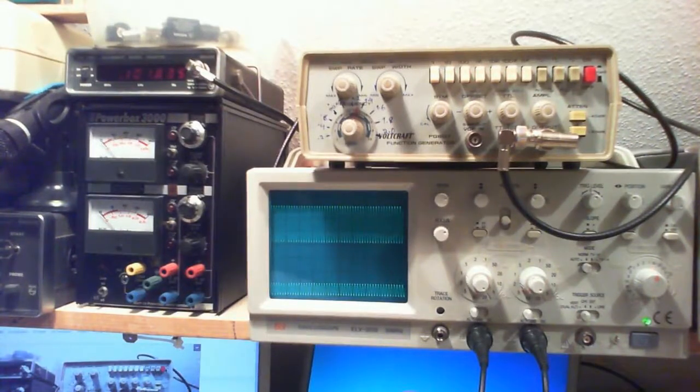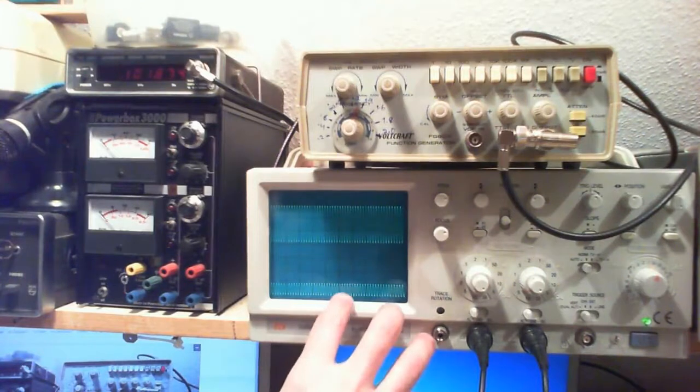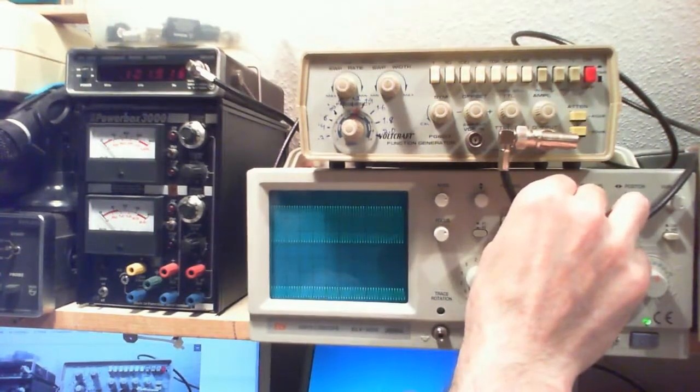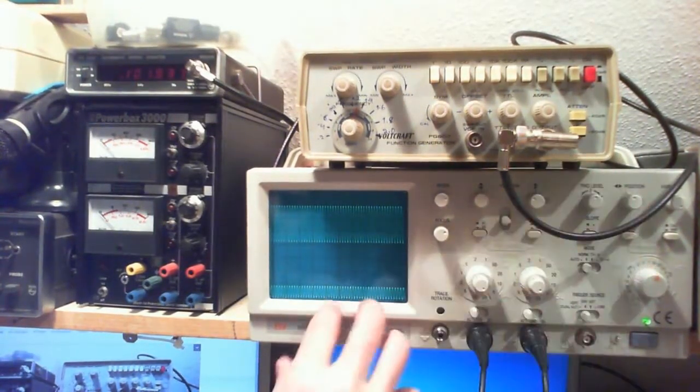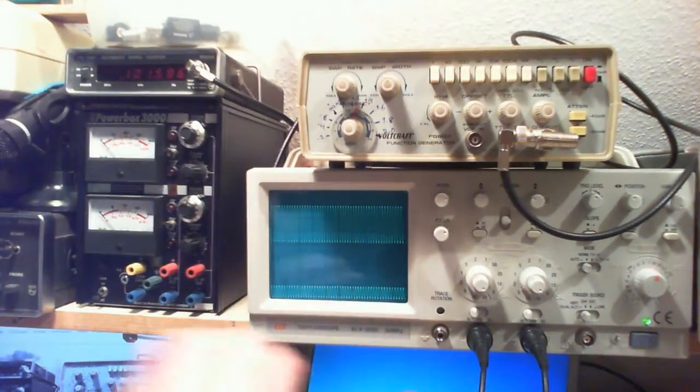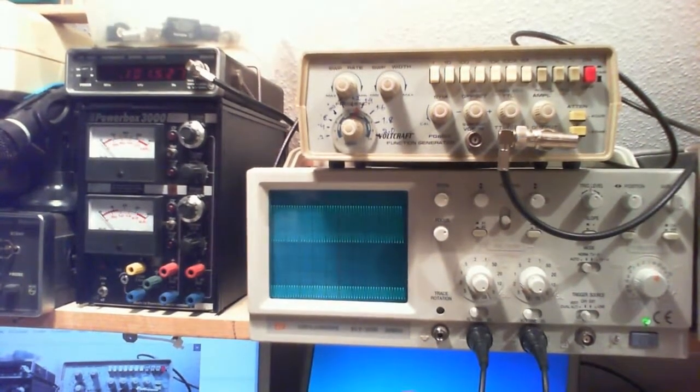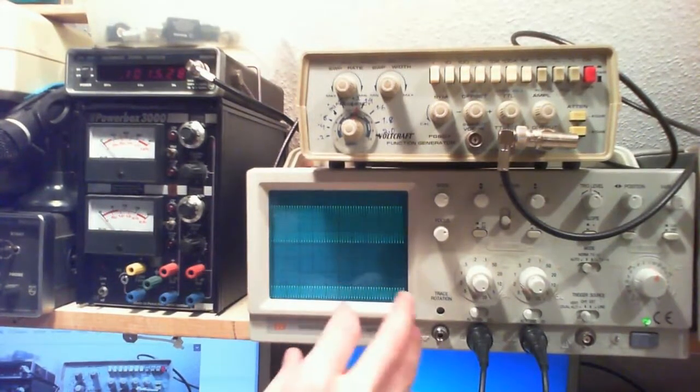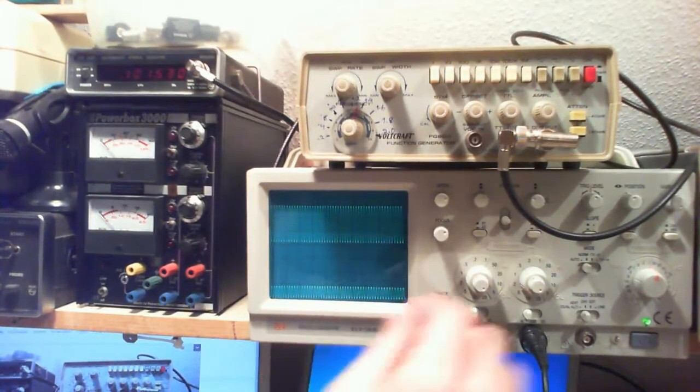Oh, I got past the resonant frequency actually. It was 50. No, that's 503 kilohertz. That's about 500 kilohertz. Okay, so right now I'm at about 100 kilohertz or so. And you see the output is at about 4 volts. It's 0.8, so about 4 volts or so.